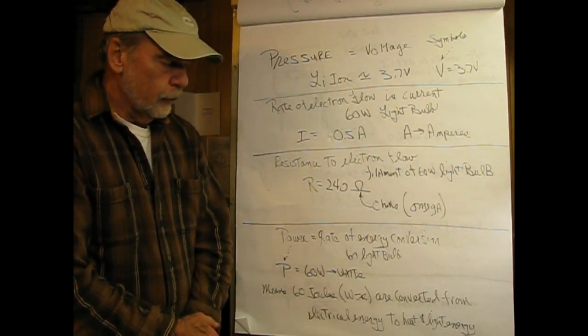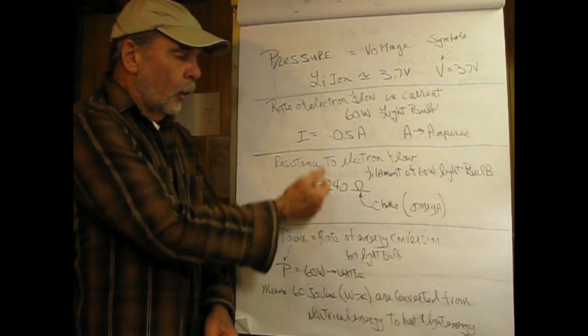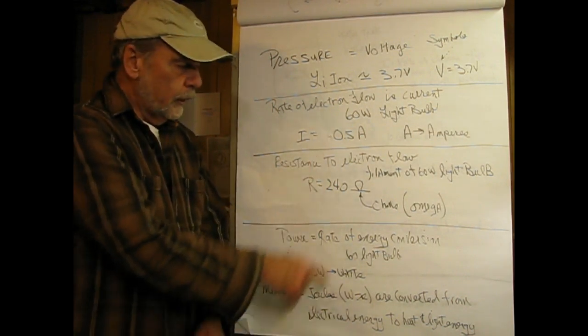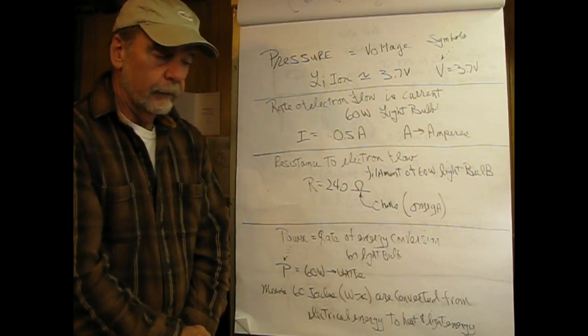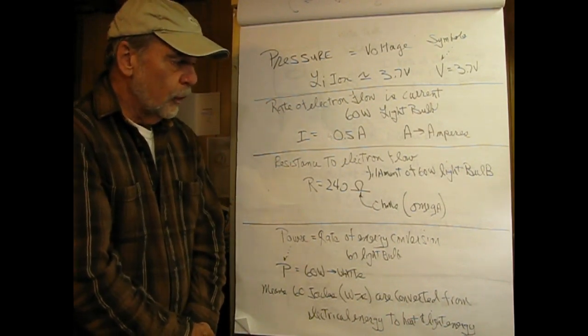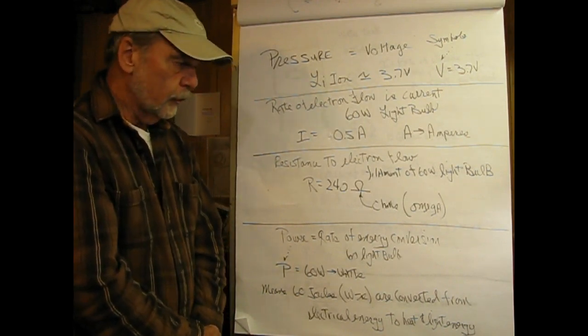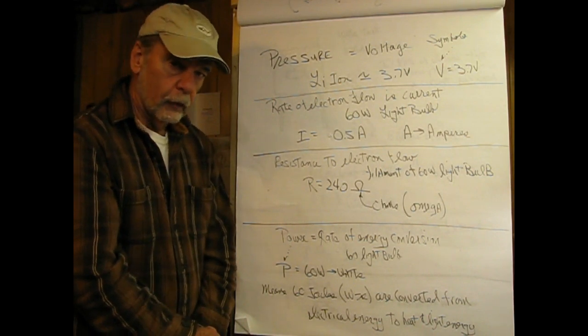The reason we do that is because numbers typically don't start with a decimal point, so if there is, say, an artifact of a copy machine noise or whatever, we might mistake 5 amperes for 0.5 amperes. So it's good practice to always put a leading zero if you have a decimal point.